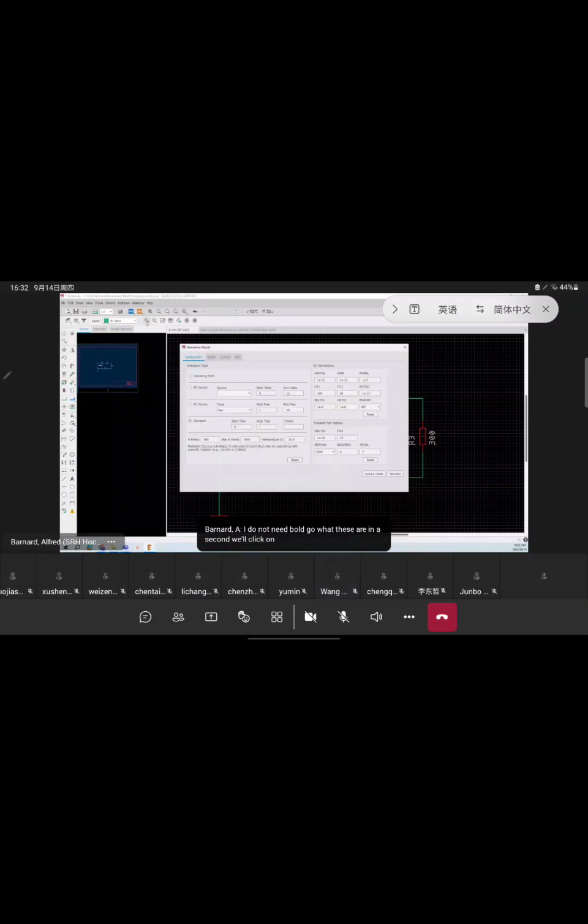We'll click on simulate. Now simulate gives you a couple of simulation types. If I have an operating point simulation, it will work around that specific operating point. So operating point means it takes one specific voltage, and then that voltage is the voltage that it's giving you. So let's do that. Let's simulate, and it'll give you these values.